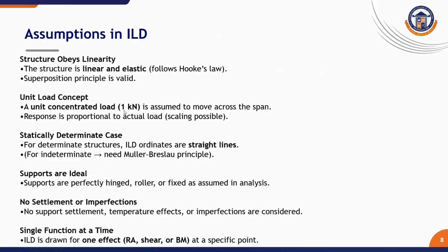Some of the assumptions in ILD: like any powerful tool, the construction of ILD rests on a set of fundamental assumptions that define its scope and limitations. Linear elastic behavior: the structure must obey Hooke's law, which means the stress is directly proportional to the strain. The principle of superposition must be valid, meaning the effect of multiple loads is the sum of their individual effects. The unit load concept: we analyze the structure for a single dimensionless unit load. The result for real loads is obtained simply by scaling the ordinates of the ILD by the magnitude of the actual loads.